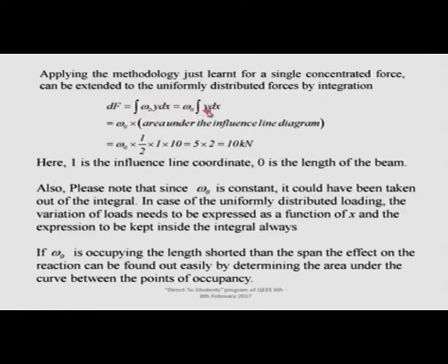Now, omega 0 has already come out of the integral because it is uniformly distributed load, but if the load is not uniformly distributed, it will be a function of x if I can express it, or segment-wise I can express it through different integrals. If I totally fail, I will have the summation over different ranges, no problem.